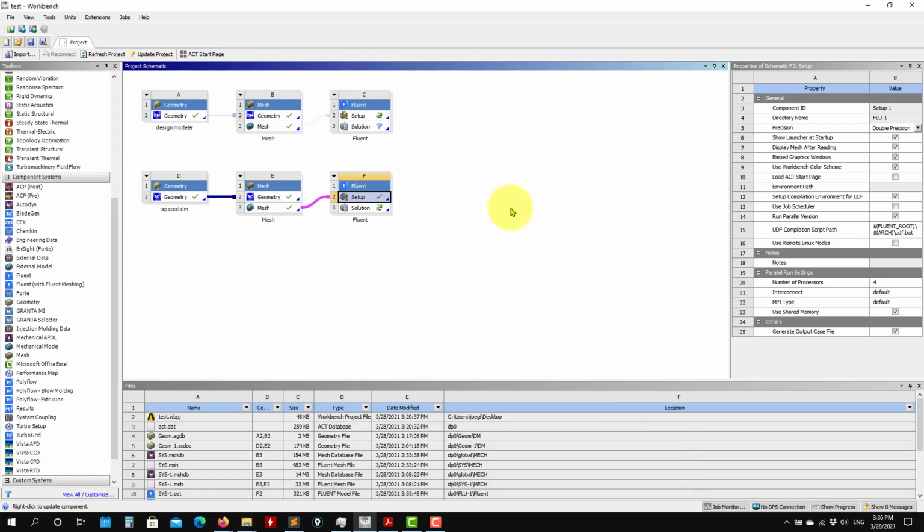So at this point, I think we're done. So remember, we ran this case. We didn't run this one because I put here a very large mesh. But you can modify this one. If you want to run using this one, remember that you need to set up your named selection for the boundary conditions. So I think at this point, I'm done with this case.